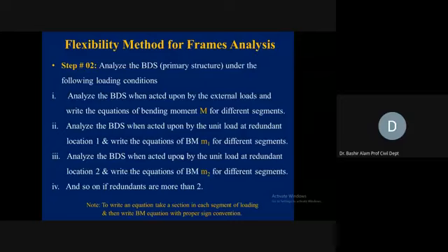This is the same which you did in the 4th semester for finding out the displacements at various points in the case of frames. You have already discussed the virtual work method. The point of interest where you are investigating the deflection, there we apply a virtual load of unit intensity. This is the same thing.